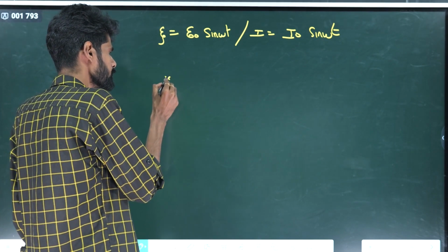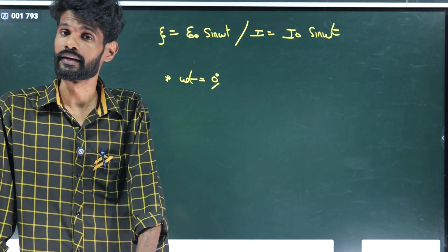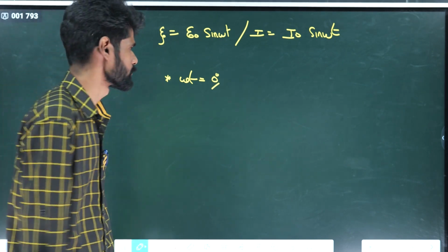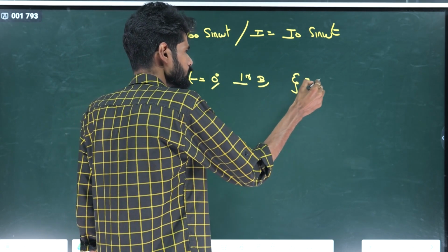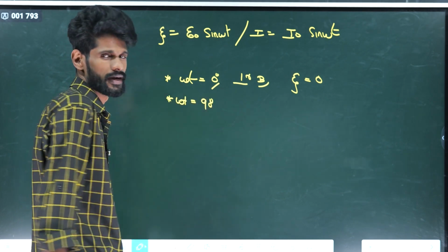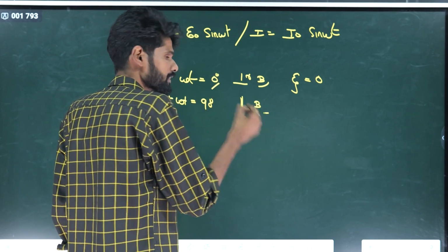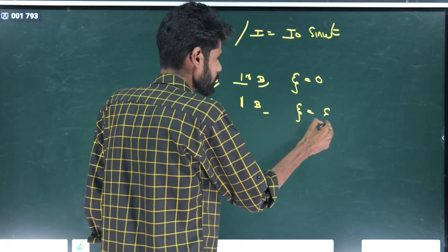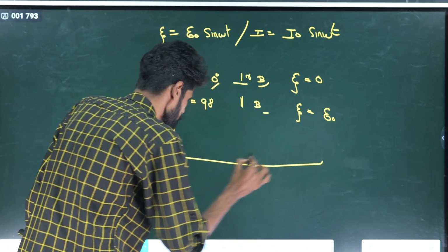Here, first putting omega t equal to 0 degrees. Omega t equal to 0 degrees means that the plane of the coil is perpendicular to the magnetic field. Here E is equal to 0. Now omega t is equal to 90 degrees. Omega t equal to 90 degrees means the plane of the coil is parallel to the magnetic field. Then substituting, E is equal to E naught. By substituting the proper values, we get the properties of that induced EMF like this.